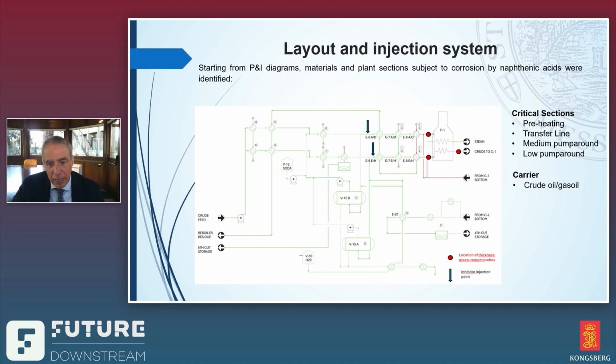the corrosion rates. Very important is also the metal of the section, because, for instance, stainless steel has a greater resistance to corrosion compared to low-grade carbon steel, but obviously the cost is higher, and so we have to protect some sections even when the temperature is lower, because of the cheaper metal in the section in which it has been designed to be so. So we have these measurement points which are upstream of the heater and at the outlet of the heater.